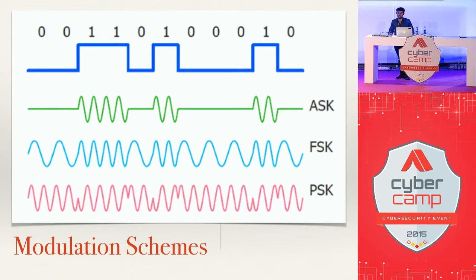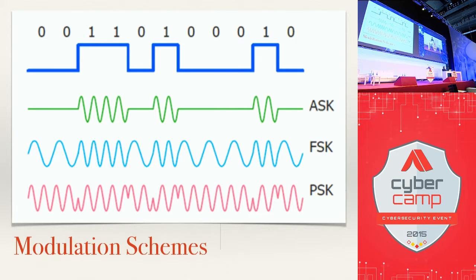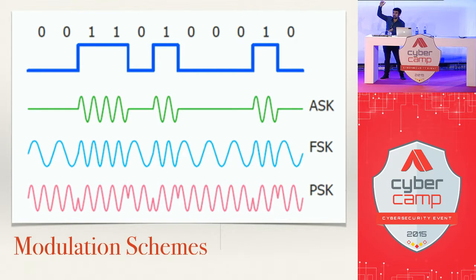So amplitude shift keying is a type of amplitude modulation, or AM. If you ever go in a car and listen to the AM radio, that's amplitude modulation. It's the same type of modulation here. It's basically where the amplitude, or essentially the volume of a signal, is going up and down. In typical ASK or OOK, on-off keying, up means 1, and no volume or no signal, no amplitude, means 0. It's a very basic way of sending digital data across an analog medium such as radio.